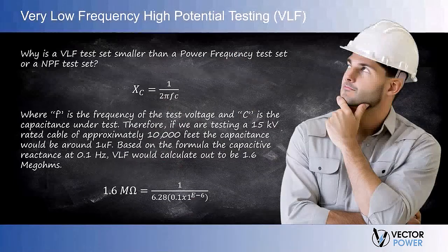Let's take a look now at very low frequency. The field industry as a whole really loves VLF testing. And the main advantage of testing at very low frequency is that it significantly reduces the size, weight, and cost of the required power supply, and thus offers greater attraction for field testing of medium voltage cables. It also makes the technology more available to a larger variety of clients.